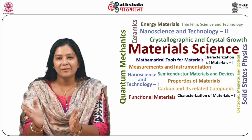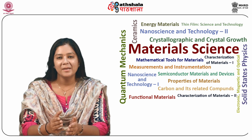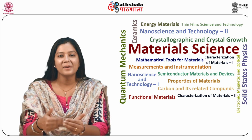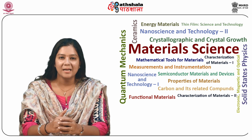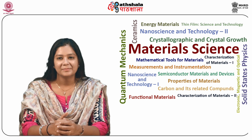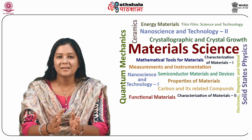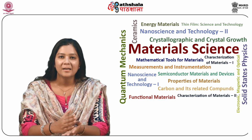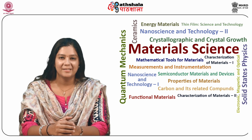These openings are further exploited to develop semiconductor regions by means of diffusion and implantation. Etching can also be used to delineate metallized layers. Chemical machining of a semiconductor is incorporated into the fabrication process by the process of etching.